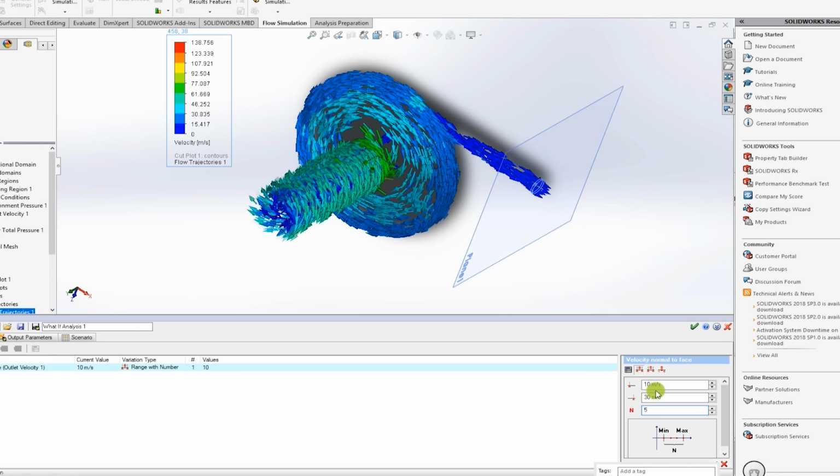Now what we are trying to do here is create a performance curve. So we are basically increasing the flow rate, and we are going to compare how the outlet total pressure is going to change. Ideally, if you have a realistic geometry, then you can actually refer to the pump's performance curve and provide realistic boundary conditions. But since we are using made up geometry, I'm just going to make up these examples. So there is a good chance that some of these examples might fail. Your task is to actually run it and explain the results that you're getting.